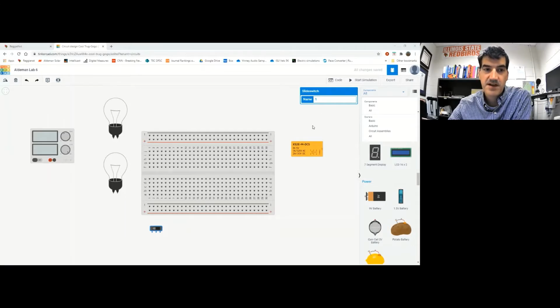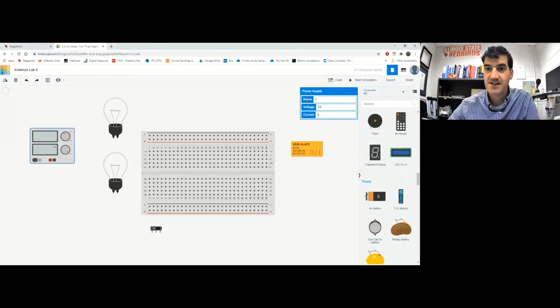And the components that I have pulled out are a double pole, double throw relay. It looks like this and looks just like the one that we talked about on page 41. And also two kind of dumb incandescent bulbs. I'm using incandescent bulbs because they're dumb and it doesn't matter if I have a series resistor to protect them or not. They're pretty easy to work with. However, as we're talking about that, I'm reminded that one thing I did have to do was change the voltage of the power supply. So remember, we had to change this to 12 volts.